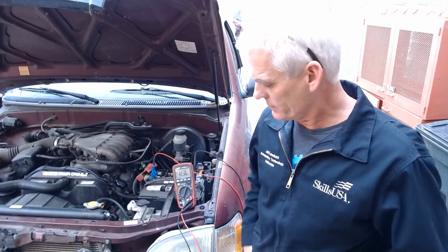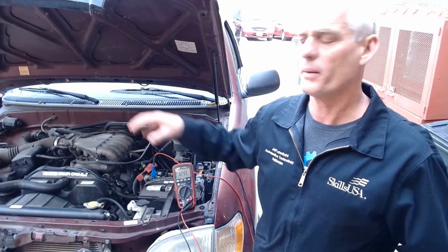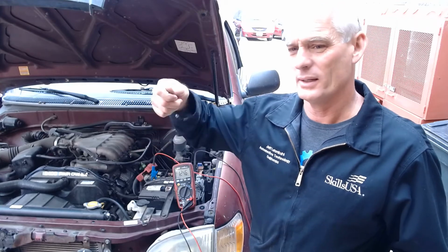But in any case, our headlight test proved valid because when it wasn't starting, the headlights did not dim, which means the starter was not trying to pull power from the battery. There's a problem inside the starter. And we're pretty sure it's inside the starter because we could hear the gear flicking out. So we know that it's getting the command and it's moving the gear out, but it's not actually spinning it.